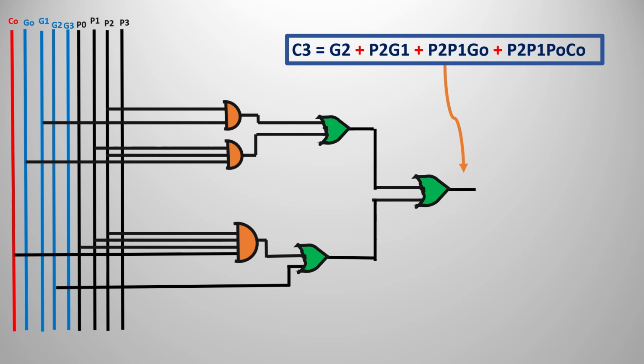For this we are going to have a 2-input AND gate, a 3-input AND gate, and a 4-input AND gate, and one 4-input OR gate. Instead of representing directly with a 4-input OR gate, I am representing it in this fashion. It is valid and that is also valid. We can represent 4 inputs at a time in one OR gate. Similarly to the previous one, we map all the things with the corresponding input lines shown above.